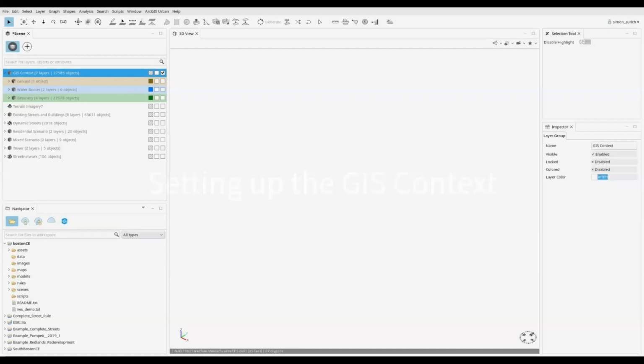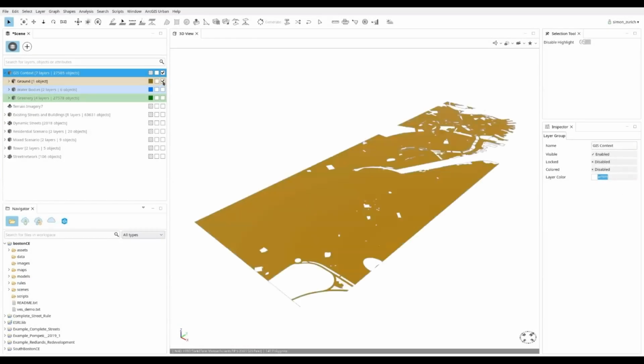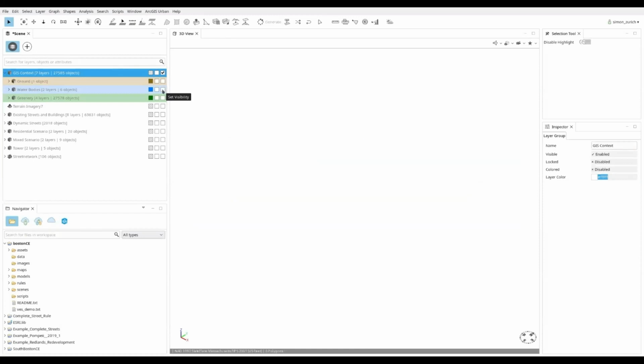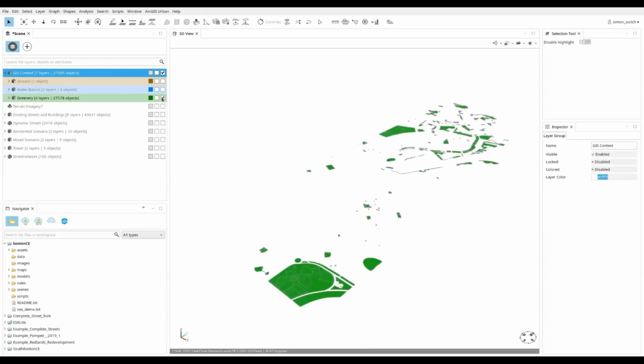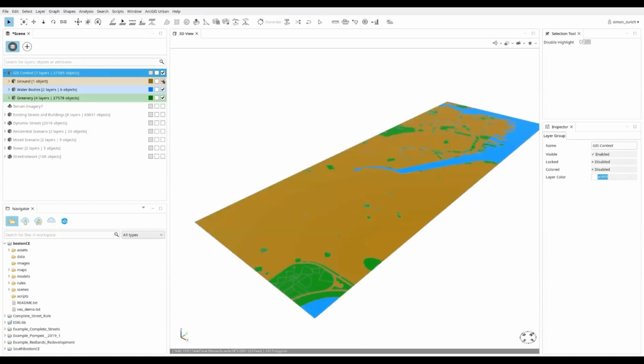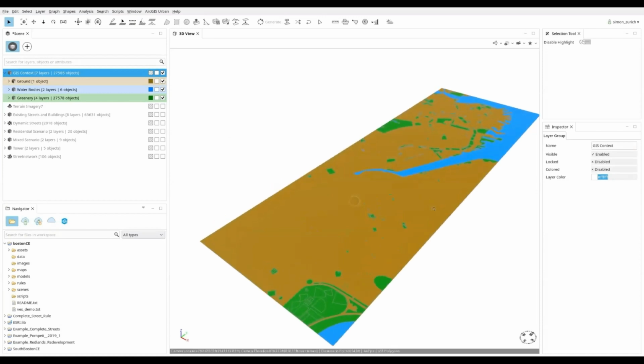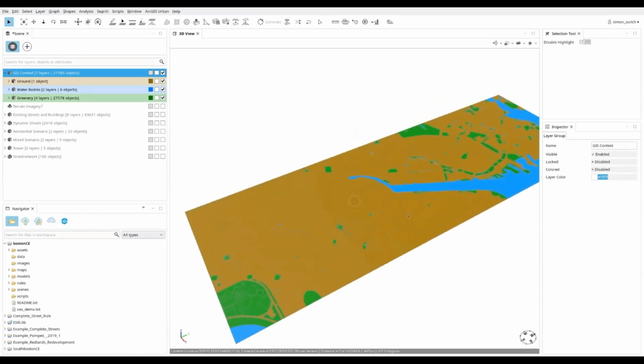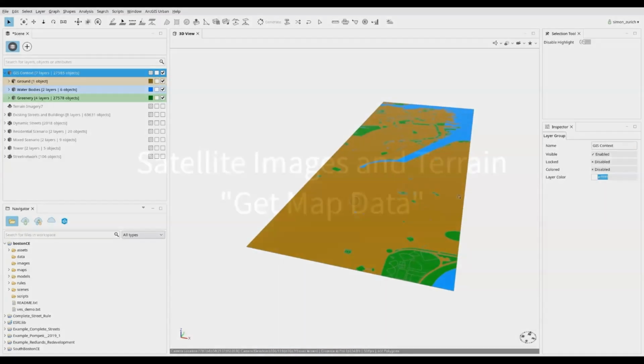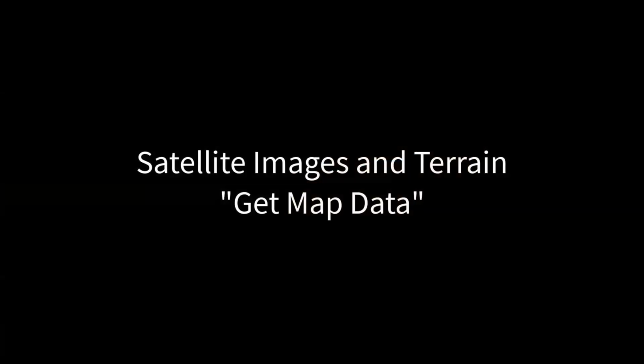So we start the CityEngine scene by importing the raw GIS data provided by the Boston Urban Planning Department. This will allow us to correctly georeference the scene in case you want to align more data later on. So it's useful to stay georeferenced in CityEngine as long as possible for such scenes. In this case, we start with large polygons, which give us the boundaries for groundwater and greenery. These are just references, they will not show up in the final scene.